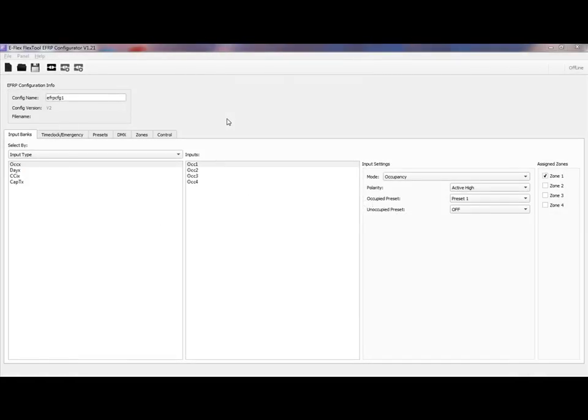In this video, we'll discuss the input programming for an eFlex relay panel. The Input Banks tab displays the user interface for programming the occupancy, daylight, contact closure, and CapT wall station input configuration settings for the eFlex relay panel.